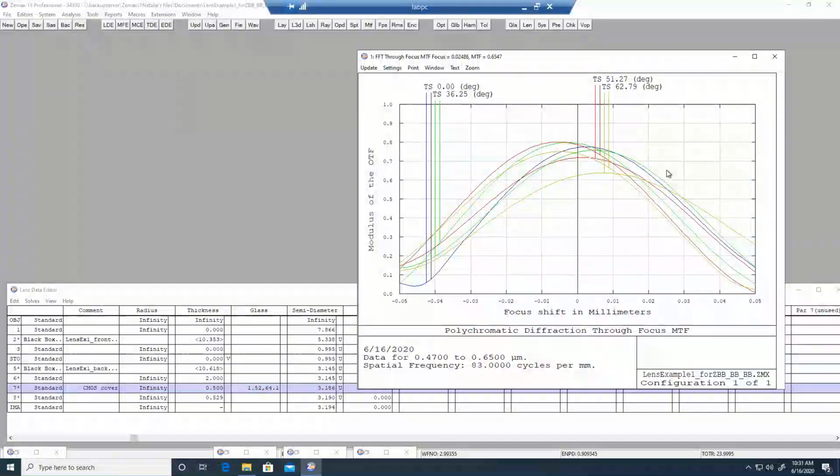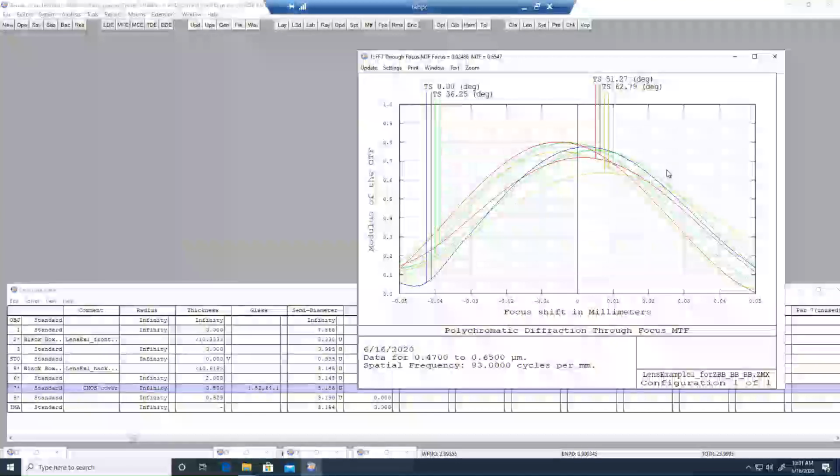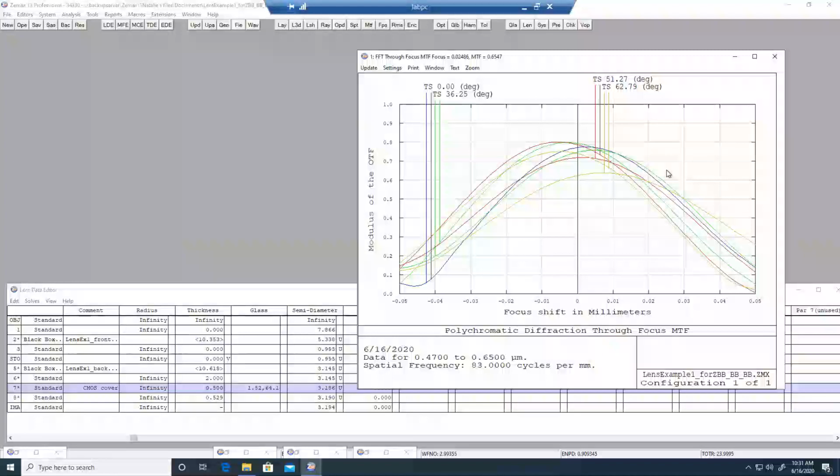Alternatively though, we do have, let's say, hyperspectral lenses. What this means is that the lens is optimized not only for visible, but at the same time visible plus 850, for example, or plus 940, or whichever near infrared wavelength. And this allows the lens to optimally function throughout that broadband wavelength range without the need to refocus the lens, which can get complicated depending on whether you refocus manually or actively. So there's benefit to that.